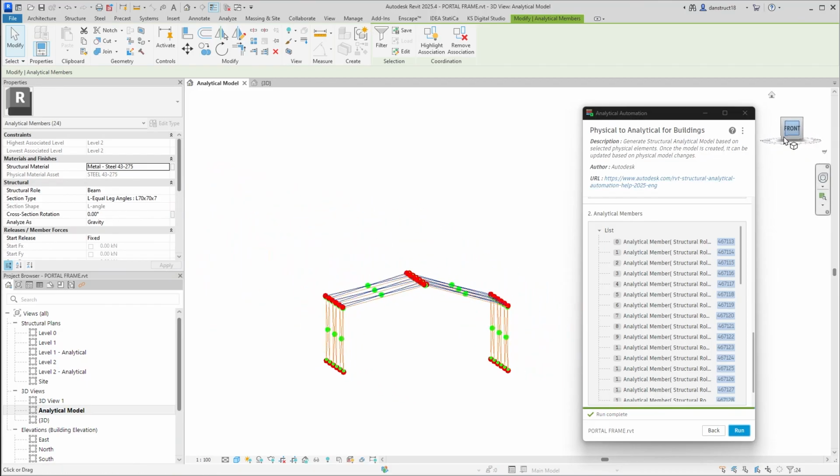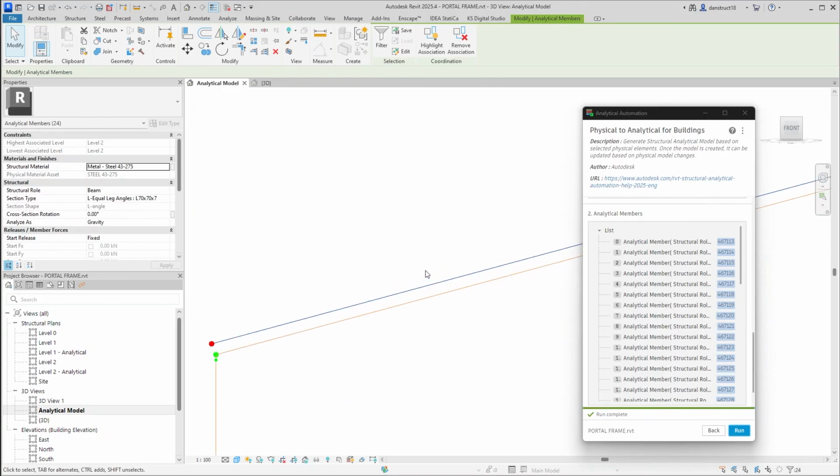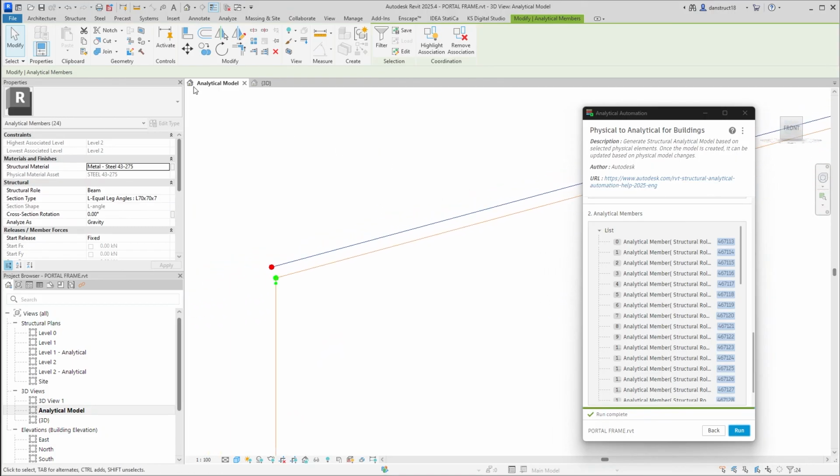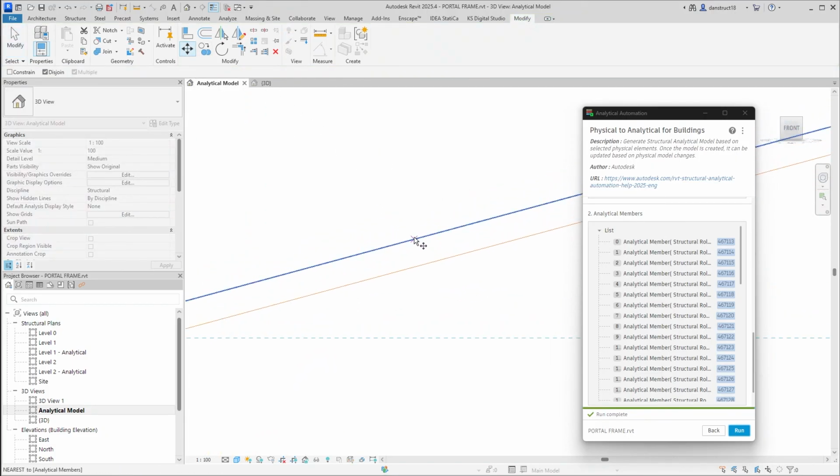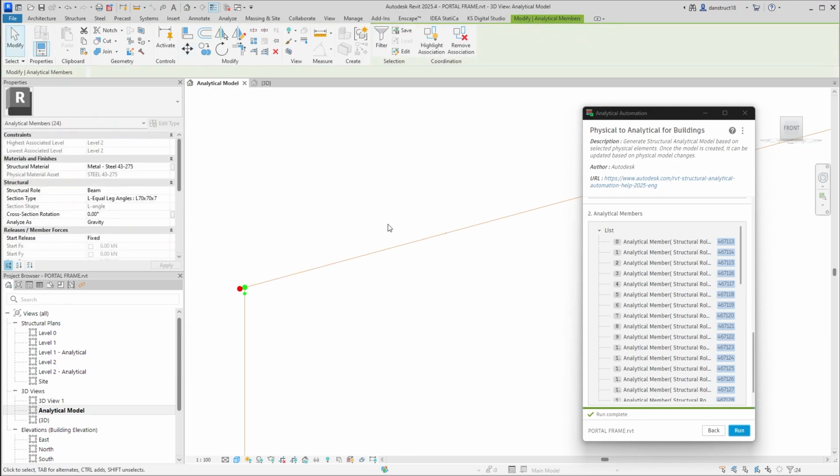Then I'll switch back here into the front or back view. Then I'll go over here and use my move tool. I'll click on this point, and I want to make sure that my disjoint button is not turned on, or else it will remove the association. So I'll turn off my disjoint button. I'll click on any line or any point along the brace, click, and then move it straight downward to meet with my rafters. There we go.